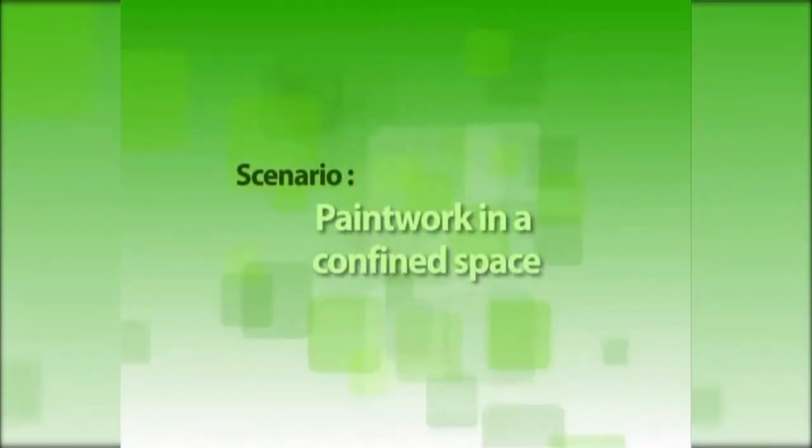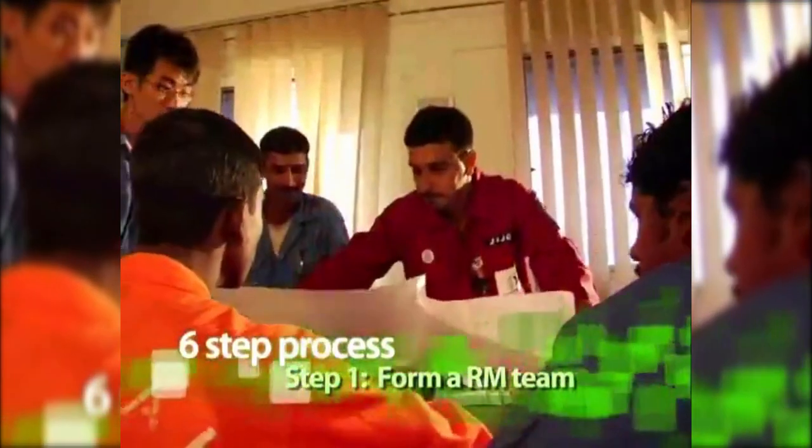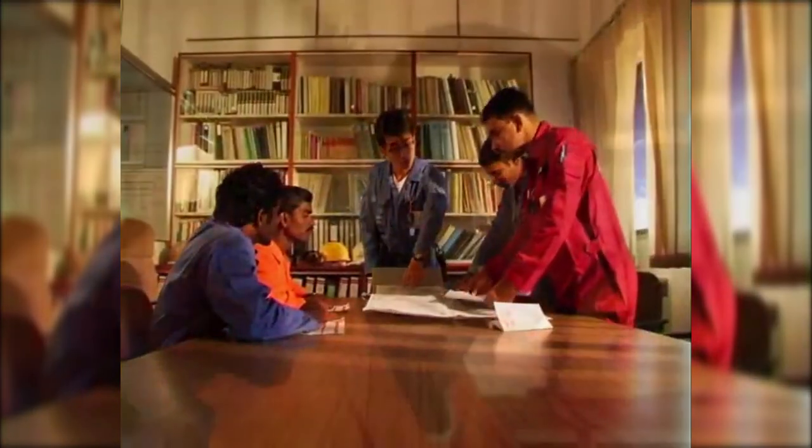In this video, we'll show you how risk management can apply to an example: paintwork in a confined space. Risk management is a 6-step process, starting with preparation. Step 1. Form a multidisciplinary risk assessment team. The team must gather all relevant safety information pertaining to the task at hand.